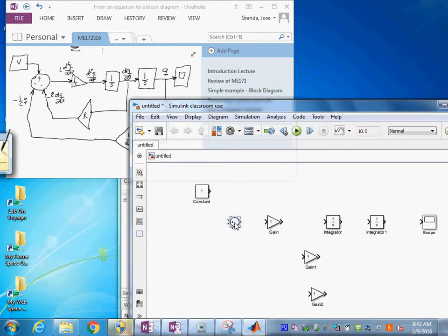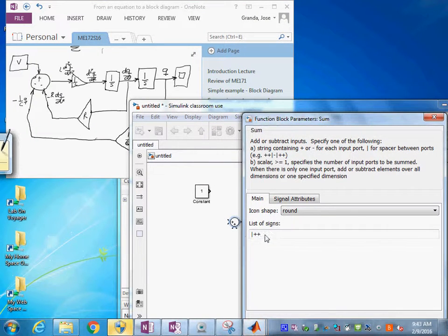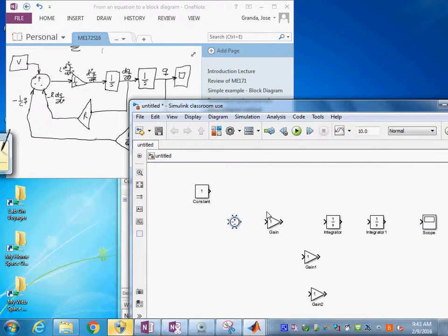I'm just going to put here V, capital V, like that. This one in here, I want you to know that if you click and then you keep the control key and you click the next one, the computer automatically draws the connection. This one right here was 1 over L, right? And then you're going to put the L in here, like that.